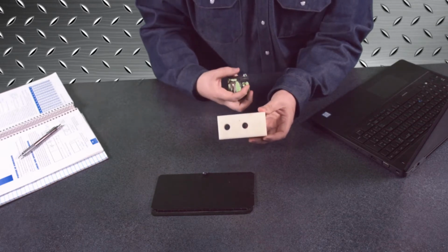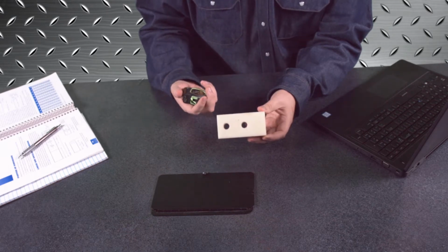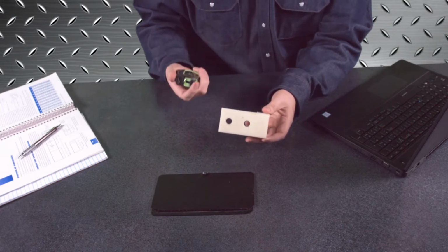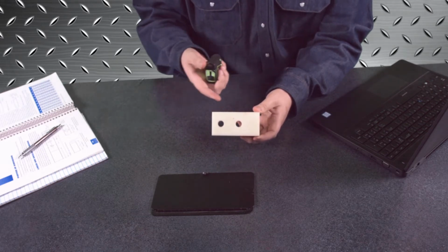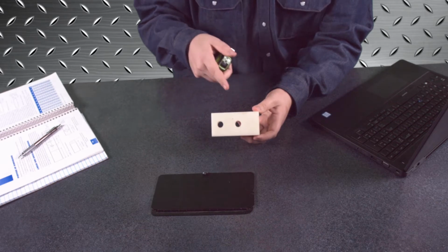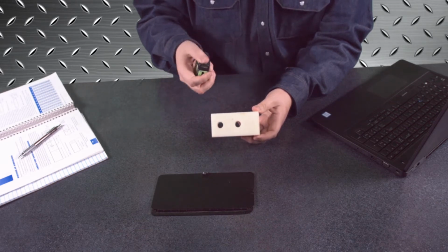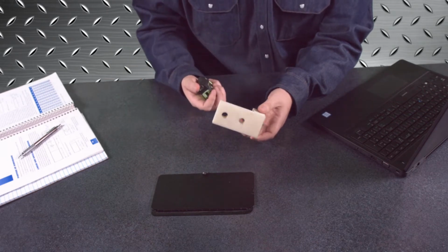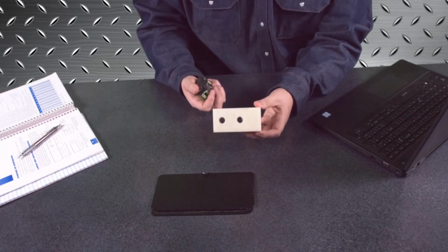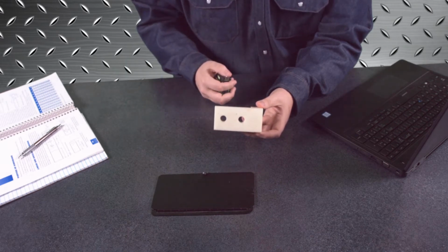The other important aspect of baseline dimensioning is you'll use decimal inches instead of fractional inches. So instead of 1 1/2 inches, it would say 1.5 inches. Instead of 1 1/4, it would say 1.25 inches instead. Baseline's usually used more for machinists in the real world, while most weldments will use conventional dimensioning.